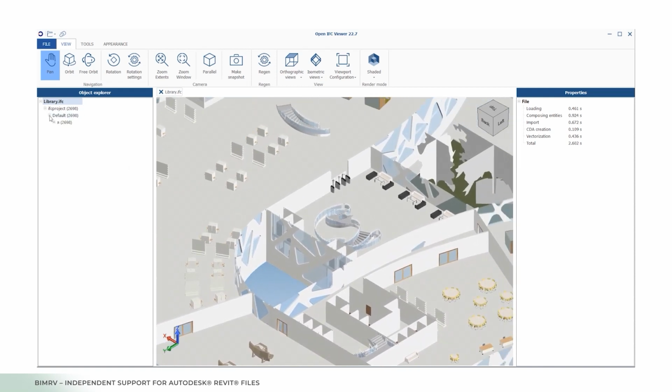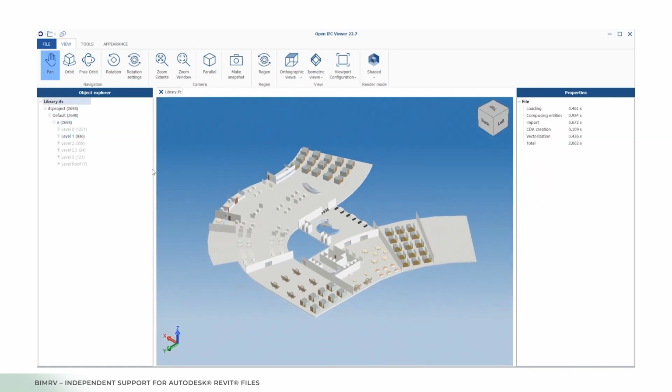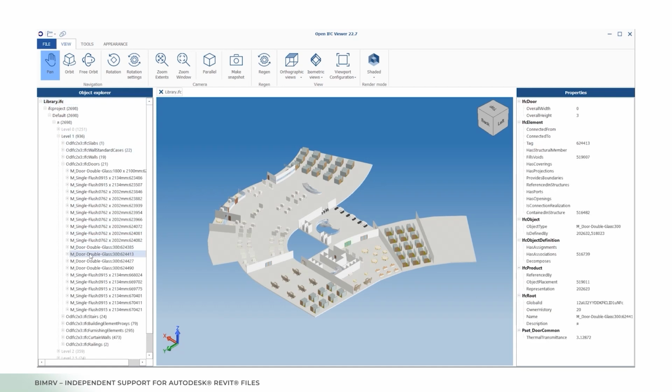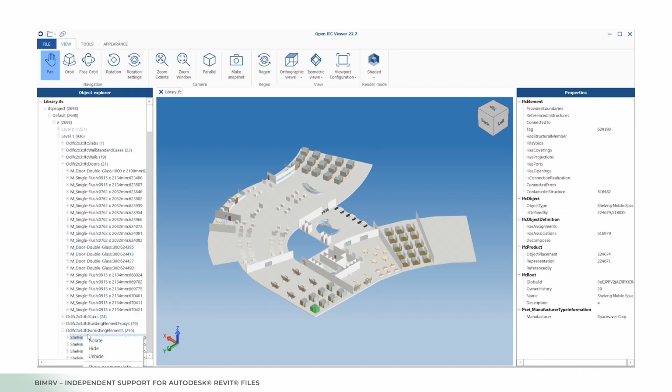Most of the 3D geometries in Revit are BREP geometry, but for IFC 2x3, we need to create meshes. In other cases, we need to create data and settings for building the geometry during interpretation of the IFC file. Each case should be researched and implemented in the export.